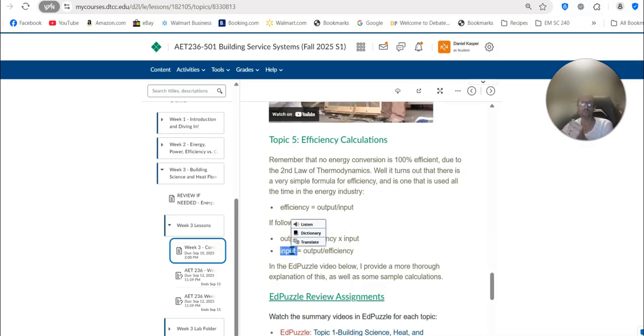Okay, and so then I know my BTUs of input, and I can easily now, as can you, convert that to whatever my heating source is. So if I'm heating with fuel oil, and I know my total BTUs of input that I need to heat that building or that space over the course of the entire heating season, then I just have to convert that to gallons of heating oil, which would be dividing by 139,000 BTUs.